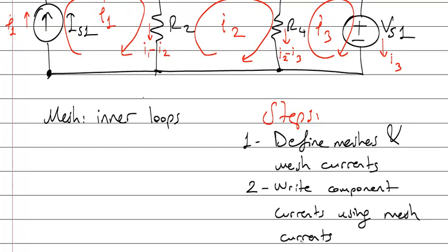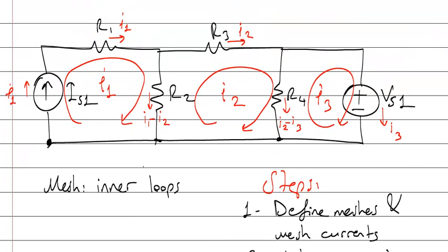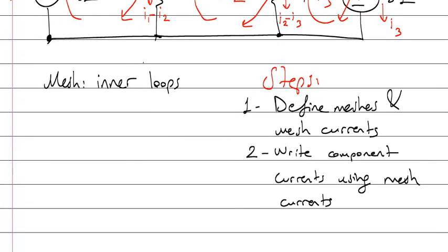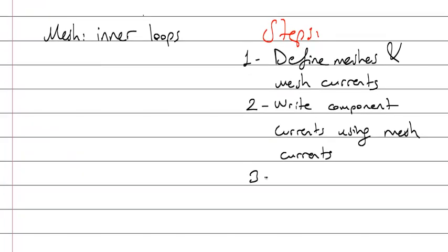Okay, I have written the currents of components in terms of mesh currents. Then the next step is write KVL equations on meshes.